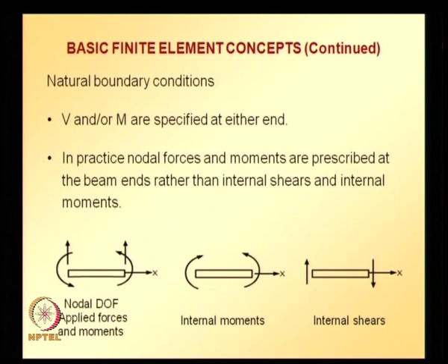Similarly, at the right hand end the applied force is in the opposite direction to the internal shear, whereas at the left hand end the internal shear is in the same direction as the applied force.